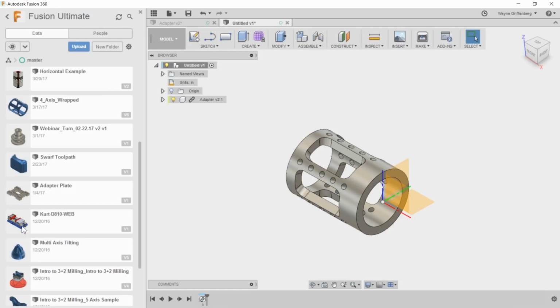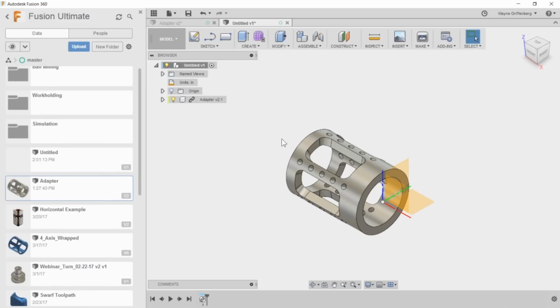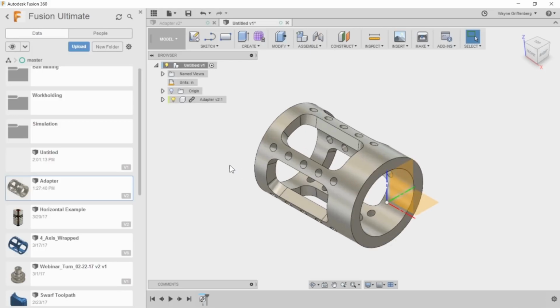So you can reuse a machine template in an assembly. And by doing so, when you import a part into that assembly, all the toolpaths will update automatically. If you're using 3D toolpaths, that is. So hopefully that helps answer the question. Yep, and yeah, this definitely showed me a workflow that I didn't know of previous to this. So that's definitely a super awesome tip.